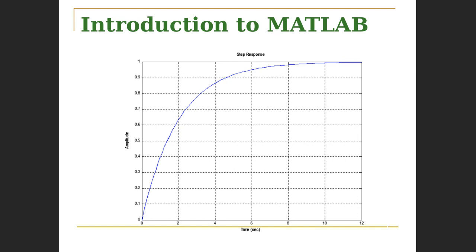So that's one way to confirm that something is happening that is consistent with what we know about RC networks. The question also could arise, how long does the system take to get to its final point? It roughly takes about 5 times the time constant to get to 99% of the value. So 5 times 2 is 10. If you look at where 10 is, it's about 99% of its final value. So by simply putting in this code, we can now analyze the response of this system.